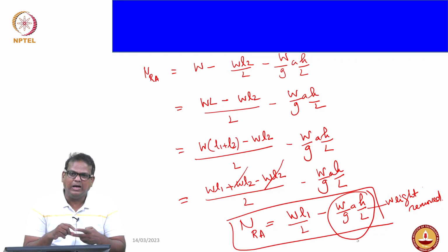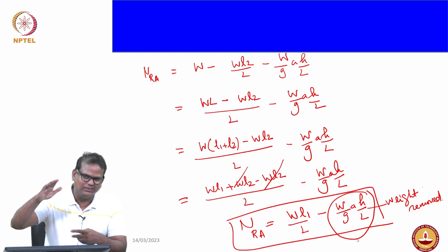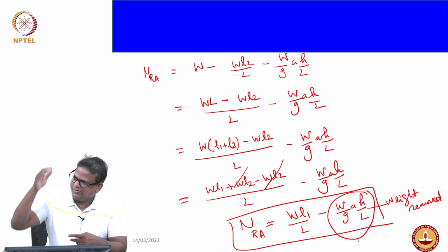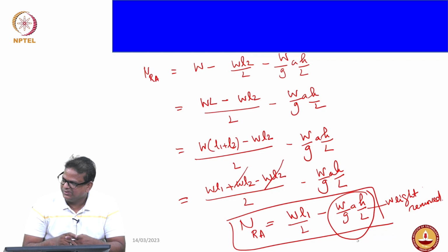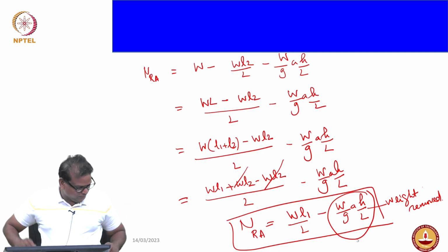And third, very important, the gradient. When the vehicle is moving uphill, that also will add up, right? So all those things should be overcome. Not only that, you have to overcome those three resistances plus the braking force. So that's what we are going to do in the realistic condition now.